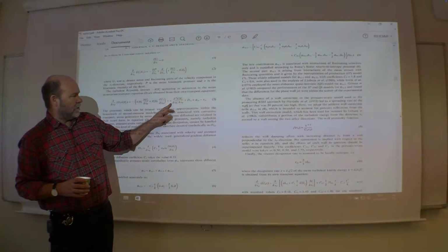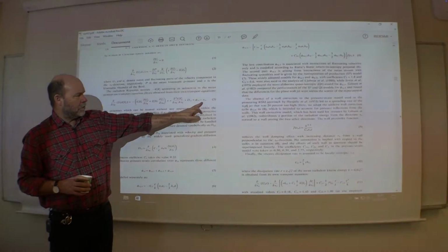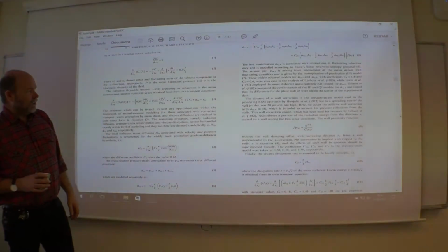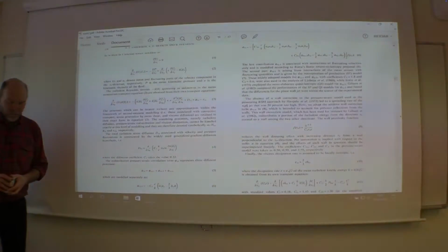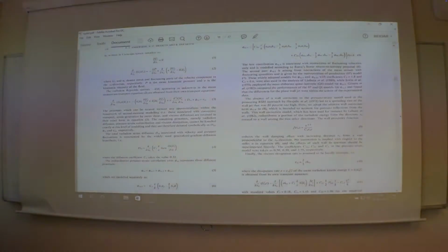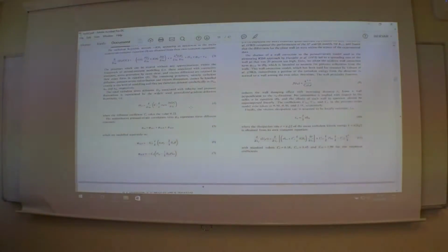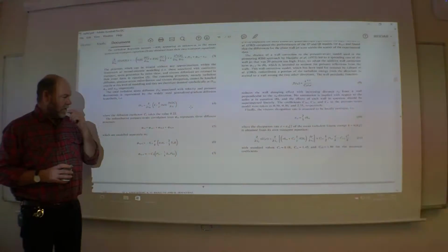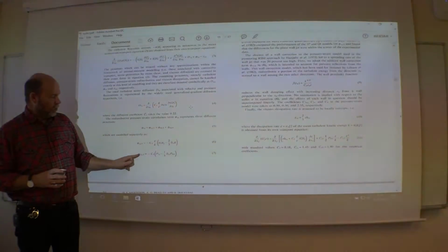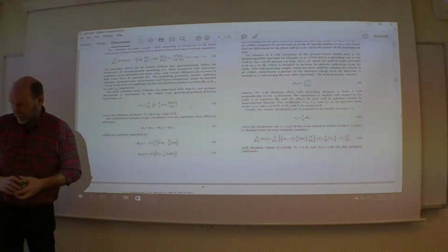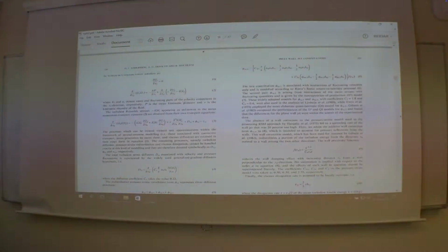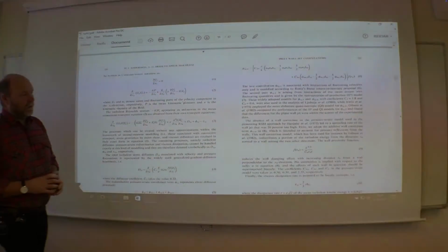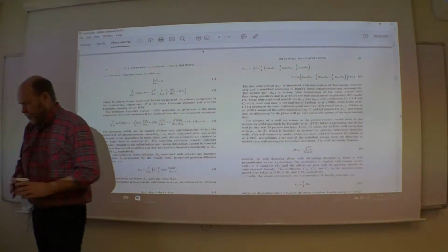The viscous term here, normally that one is included into the epsilon. Here the redistribution terms that can take energy from one of the Reynolds stresses and give it to some of the others. And then you have a whole bunch of different wall models as well. And that's sort of the focus of this article. And as you see, they can be quite complex.